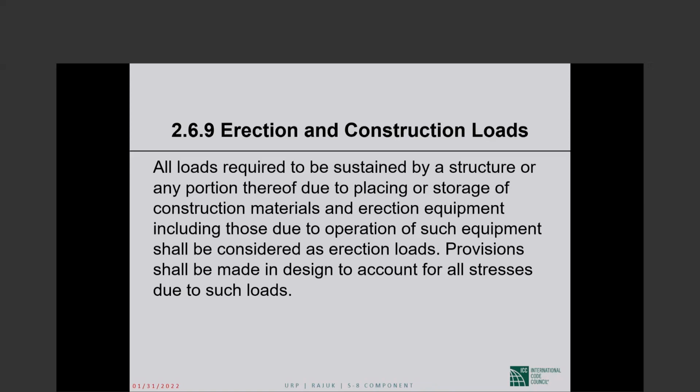There is no formwork in the picture. Okay, and those reshores should be kept in place for quite some time, in order for the slabs not to deflect too much under these construction loads, the stored material with people walking around, etc. So that's how construction loads are.